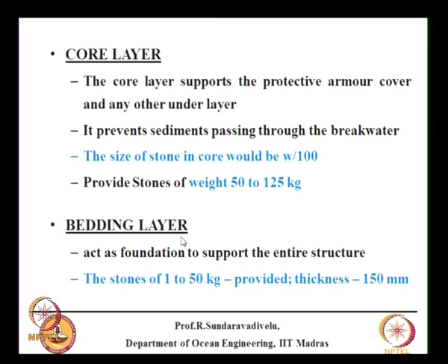The bedding layer is between the core layer and the soil seabed. Depending on the soil type in the seabed, you have to provide the bedding layer. The purpose of the bedding layer is to act as a foundation to support the entire structure, and we provide stones of size 1 to 50 kg and the thickness is typically about 150 millimeters.